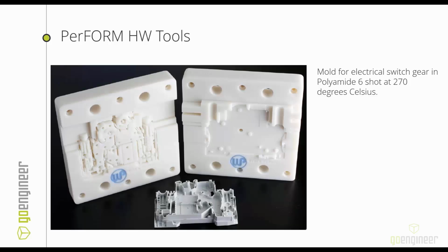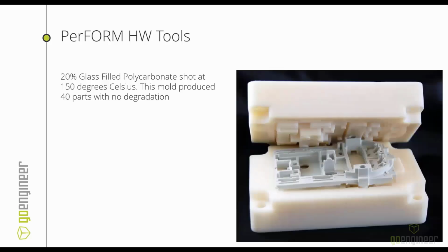It kind of depends on what you need the mold to do, the geometries it needs, and the temperatures you're going to be shooting into it. The lower the temperatures, basically, the more shots you can get out of a mold. But it also comes down to the causticness of the material. When you have glass filled and stuff, that's going to wear away and grind at your material quicker too.